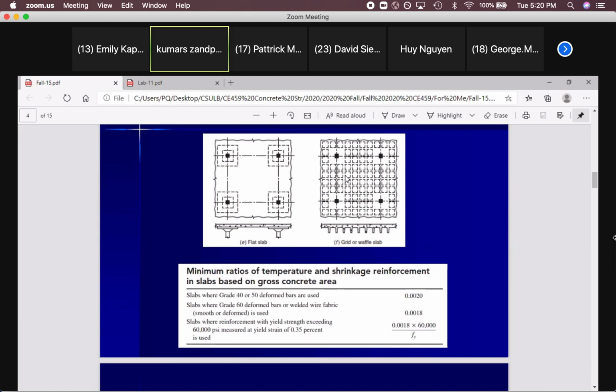And over here, those are voids. As you can see, there is a hole here. There are some voids here, so they can reduce the weight. But because you have thicker elements for tolerating the shear and bending, you can transfer more load than with just a small uniform thickness. Here is a kind of flat slab, but it can tolerate more load.